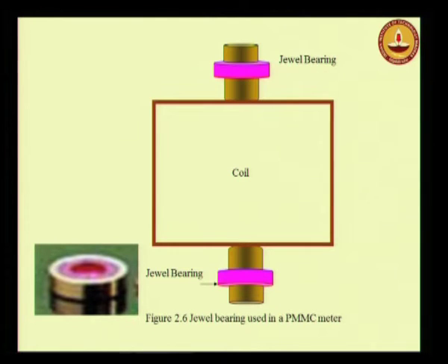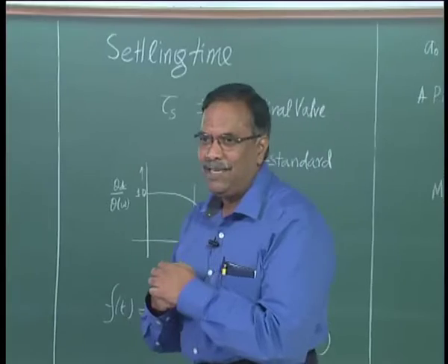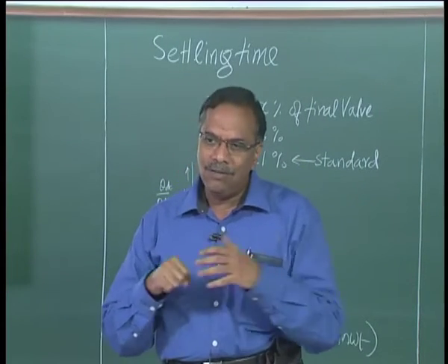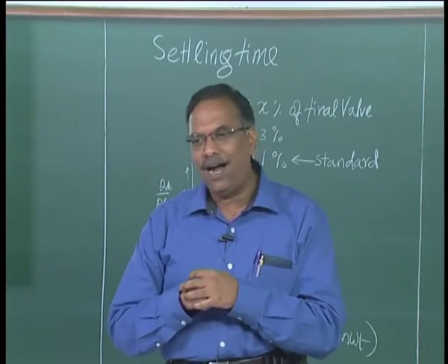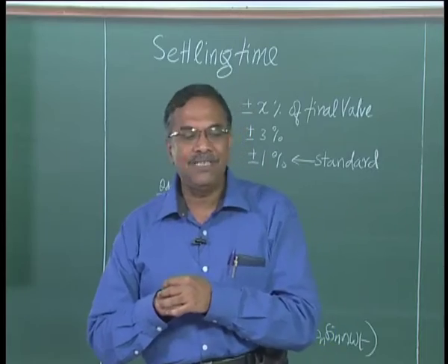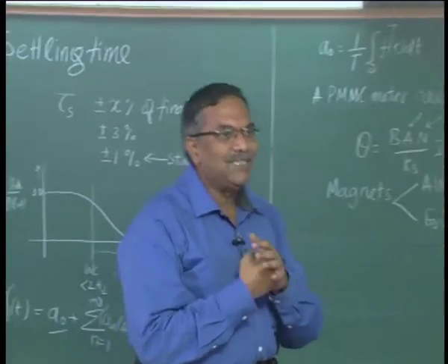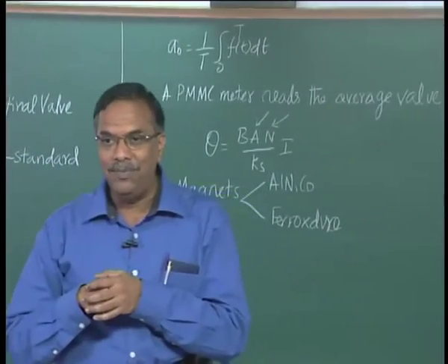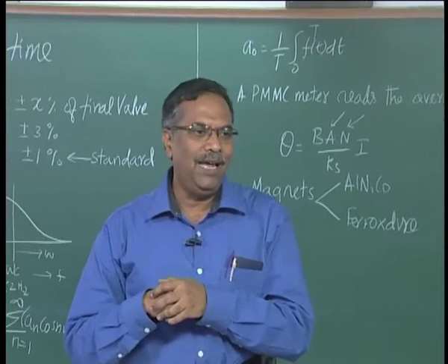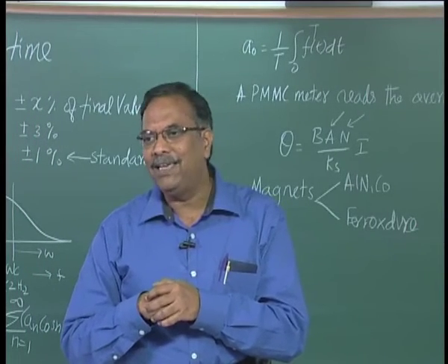For example, if I put, let us say, steel on steel, the friction coefficient I will get is about 0.6. If I put steel on emerald or ruby, right, hard stone, then the friction coefficient becomes 0.15, which means it is going to be very smooth, it is not going to rub, the friction is very small.